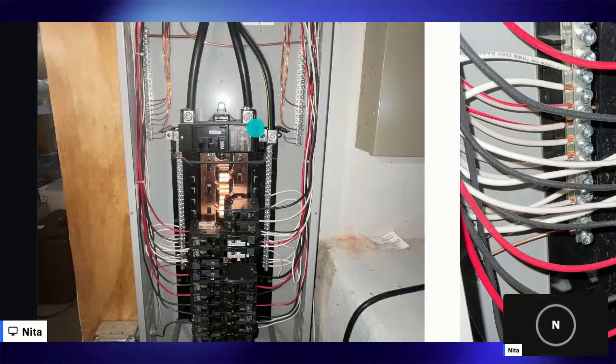Remember, these are service entrance. The service entrance conductors are going to be the largest conductors in the box. The two hots are going to be connected here to our main bus board, powering all of these breakers. The neutral is going to be connected to its own bus bar. This is the neutral bus bar. On this bus bar, we are going to see typically white wires that represent the neutrals. There is another bus bar that is the grounding.